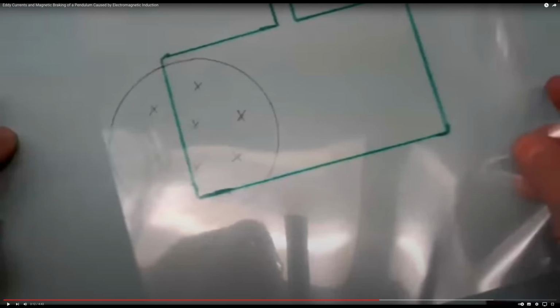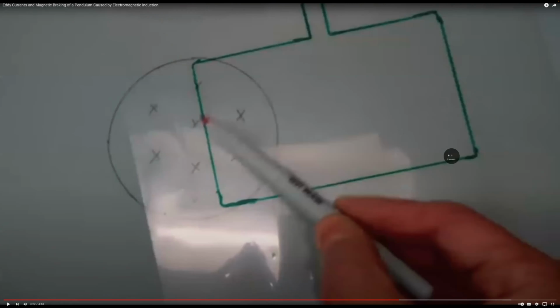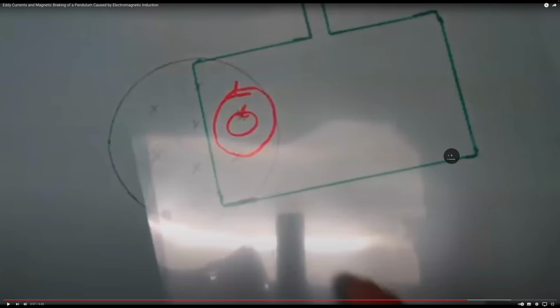So there will be small values of anti-clockwise currents flowing in this plate, and those small currents are what are called eddy currents. Observe, this is the way currents will flow. Eddy current is also known as Foucault current, though this word is not much used. Eddy current is the textbook term. They also use the word circular currents because these currents are always in circular loops. Are you able to understand this concept?